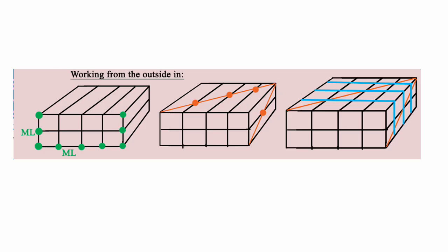To draw the grid on this box, start with 2 measuring lines with equal units and draw the horizontal and vertical lines, then continue them as converging lines to the vanishing point or set up another measuring line back here. Then draw the diagonals like this and this. And then you can find these blue lines where the diagonals and the black converging lines meet, and also on the sides, these vertical blue lines.